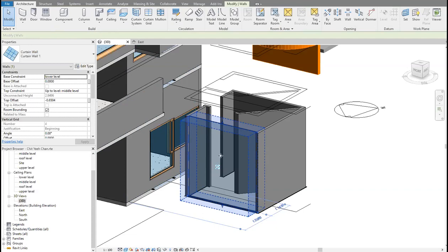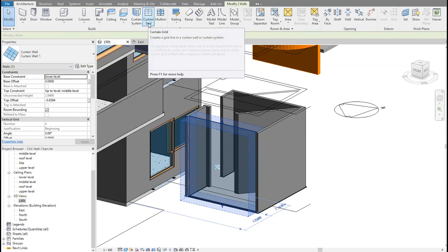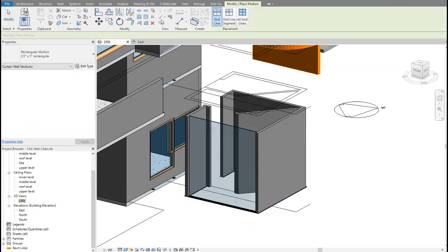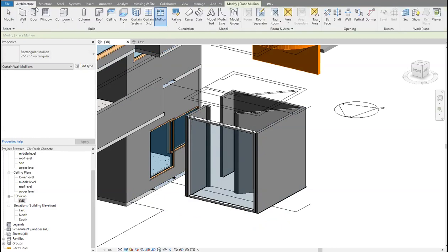So in Revit, you cannot draw a mullion like this unless there is what you call a curtain grid, which is in architecture here. By default, the limitations here are curtain grid, which means automatically you can create mullion in the limitations. You just select it and you start clicking. Now I will not be able to make one in the middle, as I mentioned, because I don't have the grid. Now how to bring the grid from architecture? This grid, as you can see here, curtain grid.